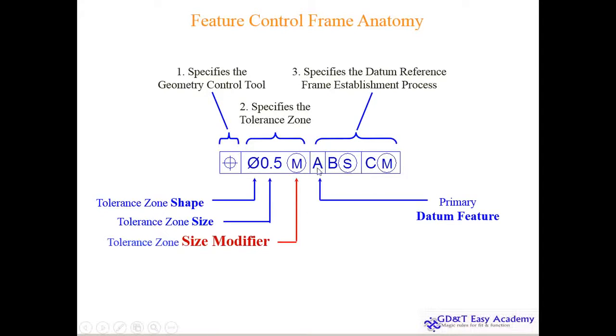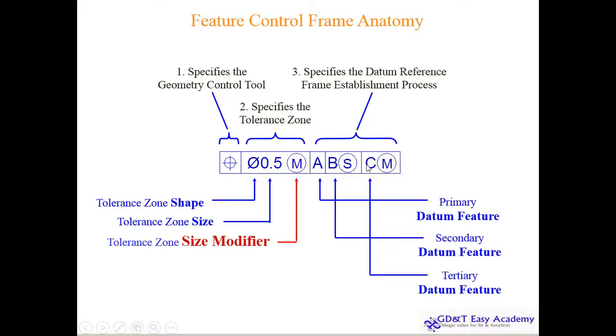And this is the primary datum, 3 degrees of freedom restricted, 2 degrees, secondary datum, and 3 degrees. Again, these are the mobility modifiers, where you can go for the rocking, or you can say the shaking of the plane. This is not absolute, the diameter change or the thickness change. So most of the people wrongly interpret this area and add it to the primary tolerance zone. So don't forget about this. If you have this type of interpretation, just change it today.